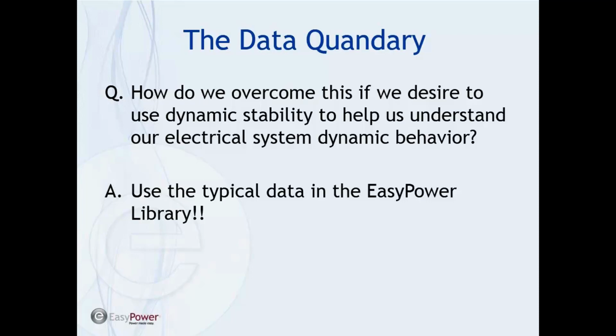Here's my answer for you. Now, you really should get your own data as much as possible, especially for machines. But if you don't have it, I'd say it would behoove us to at least use typical data values so that we can see what the possibility of happening is. If we haven't got it nailed down exactly, let's at least get some simulations under our belt that give us some ranging of effects that could be happening on our system. And we supply you a host of typical data for every dynamic stability model in the EasyPower library.